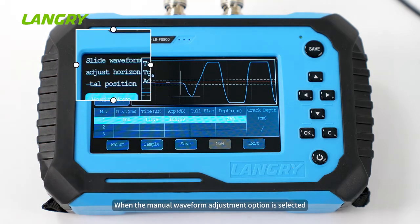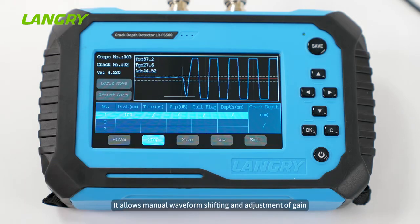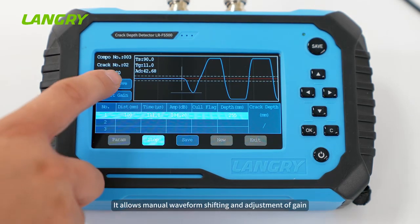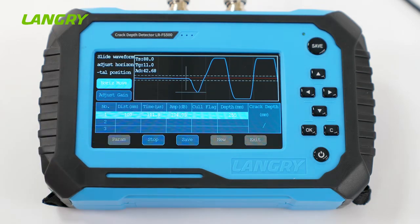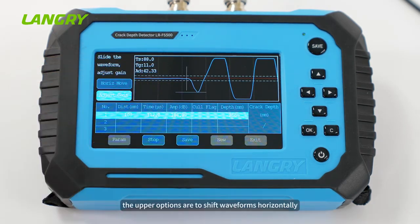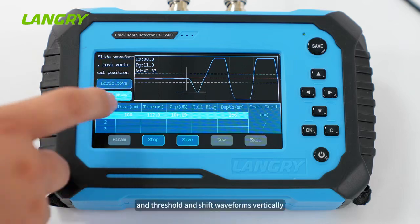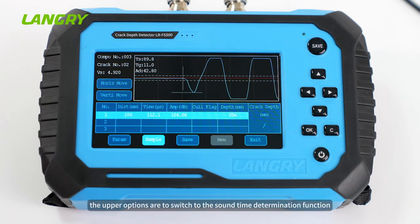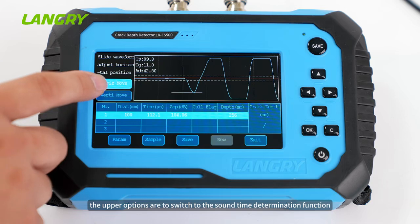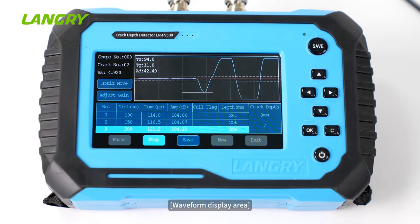When the manual waveform adjustment option is selected, this area provides an operation prompt. Manual adjustment area. It allows manual waveform shifting and adjustment of gain. Different adjustment functions can be switched depending on the testing state. During sampling, the upper options are to shift waveforms horizontally. The lower options are to adjust gain and threshold and shift waveforms vertically. When the sampling stops, the upper options are to switch to the sound time determination function and manually adjust the sound time available.